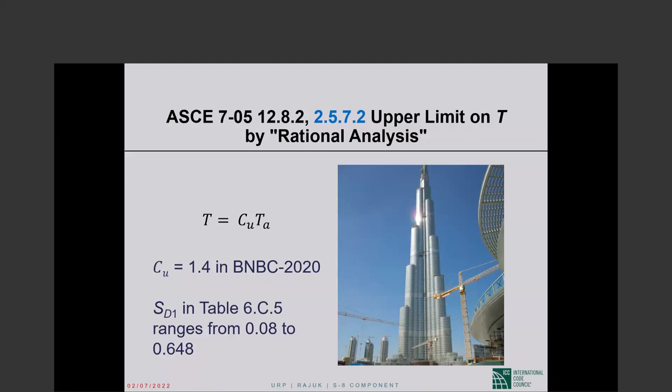If it is a concrete building or a masonry building in particular, by taking cracked rather than gross stiffness, and by taking cracked stiffness low enough, you will be in a position to calculate a period as long as you want it to be, which then will give you a design base shear as low as you would like to design for.